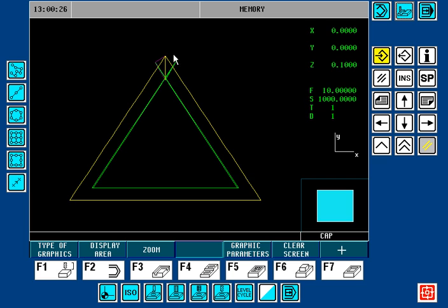So once you activate cutter comp, it's only tangent to the first surface. And if you remember from our previous discussion we had about step and path, the cutter comp look ahead in conversational is only 1 or 2 blocks. So we have 1 block, 2 blocks. This is our 3rd block. So the control cannot see the 3rd path. It can only see the 1st and the 2nd.